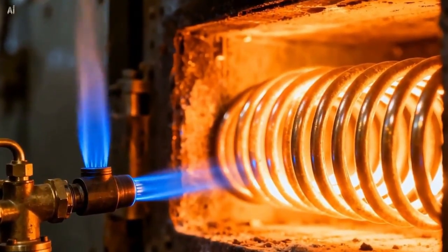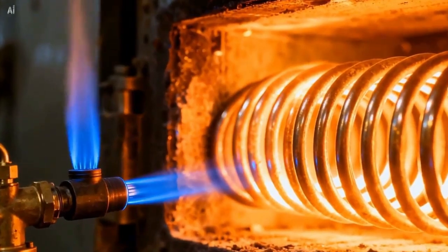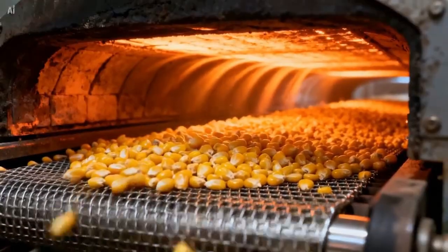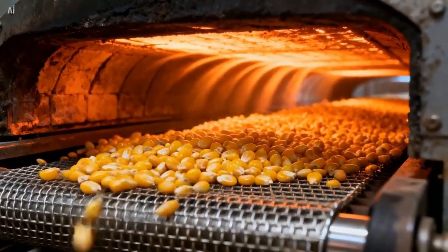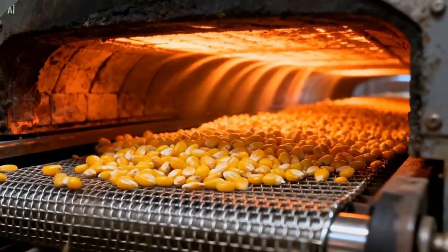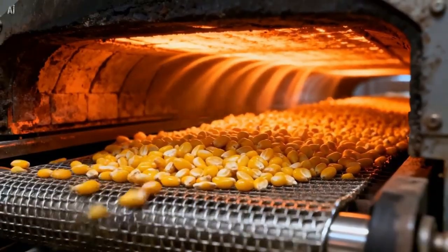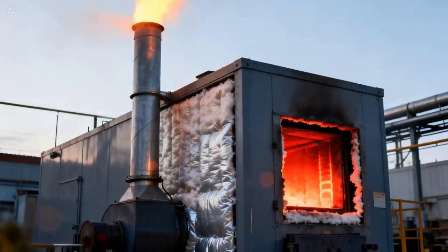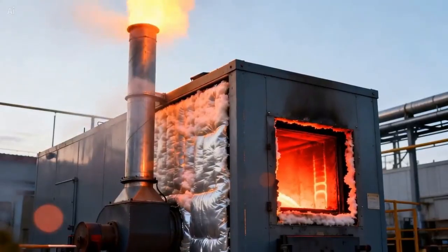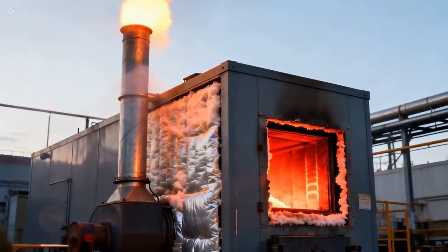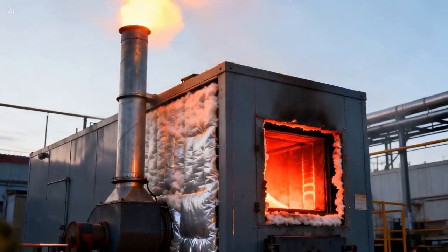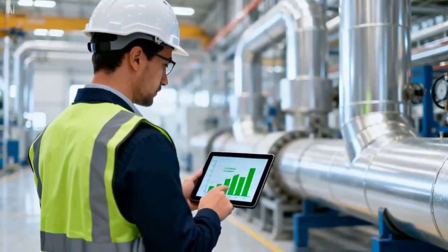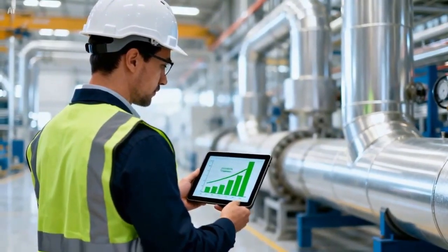In this model, the incoming heat flow comes primarily from the lower calorific value of the fuel or the electrical power of the heating elements. This energy is divided into three components. First, the useful heat absorbed by the load, referred to as Q load. Second, the sensible heat carried away by the exhaust gases through the chimney. And third, the inevitable heat loss through the walls. Our job as designers is to maximize payload capacity and minimize losses.